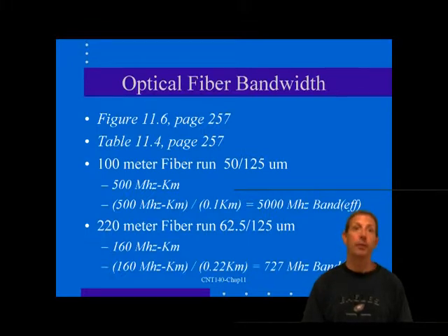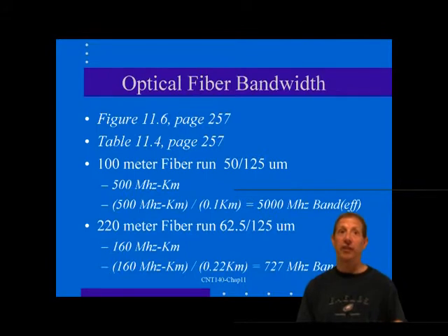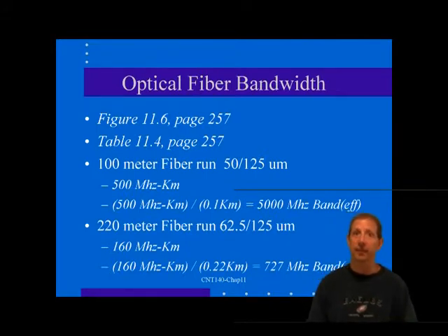The standard specifies a minimum of 2 cables to each work area outlet, one of which will be fiber. However, it does not prohibit placing more than 2 cables to a work area. Virtually all modular cover plate designs allow at least 4 module inserts. So the optimum solution for today and the future is to place 2 copper cables and 2 fiber cables, single mode and multi-mode, to each outlet box. If you use the new SFF fiber connectors, the Cat5e or Cat6 copper modules, you should be set for applications many years to come.